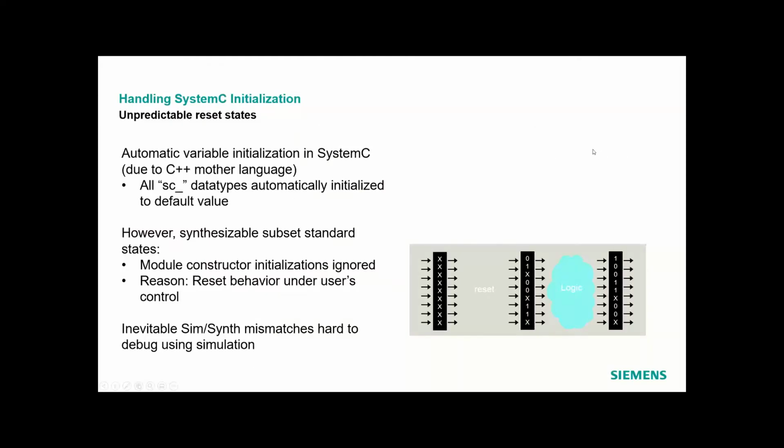Let's start now with some problems in SystemC designs and SystemC flows. Definitely how SystemC handles the initialization part, because that can cause some unknown issues. You know that by the synthesizable standard, module constructors' initializations are ignored. The reason is that reset behavior should be under user control.